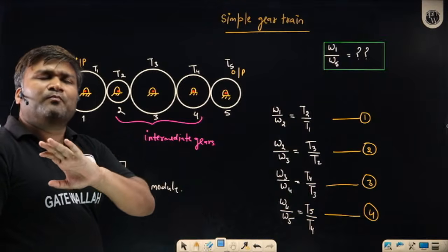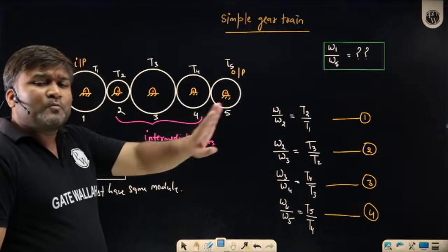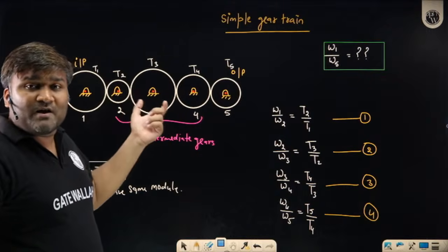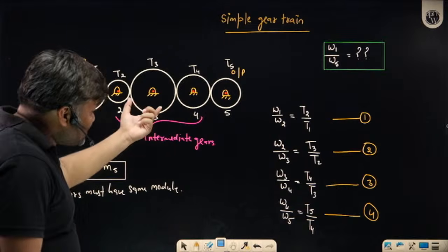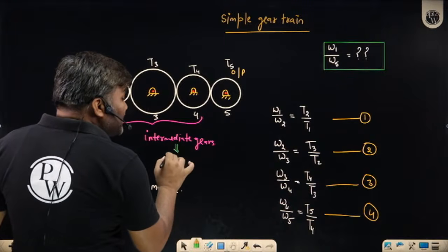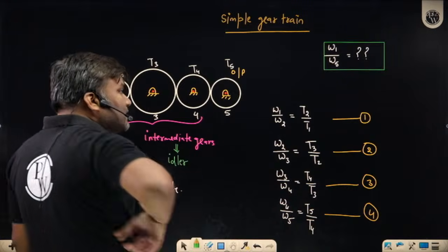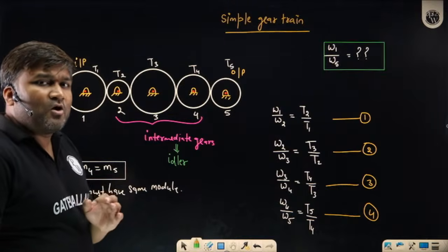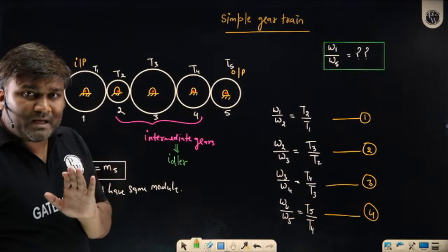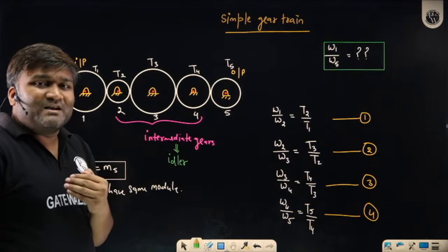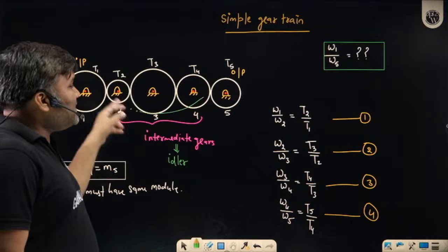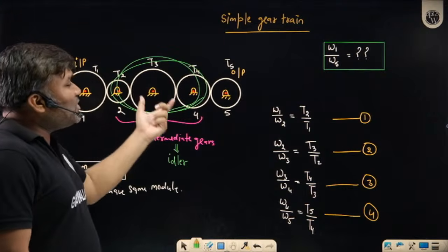Sir, I scanned all the shops of my area. Then I found these gears of the same module but different numbers of teeth. And these are not even participating in the velocity ratio. That's why these are called idler gears. They are just acting as a transmitting body. They are not contributing anything good to the velocity ratio. My main intention was to get an exceptionally high velocity ratio. That's why I have used these gears, and they are not even participating.